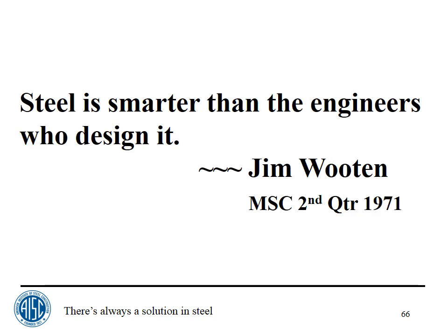Jim Wooten, an engineer who worked for a large fabricator in Little Rock, Arkansas, and passed away a few years ago, wrote an article called Wooten's Third Law that was kind of railing against some of the things that he was seeing engineers requiring, hotspot stresses and things of that sort. And he said that steel was smarter than the engineers who designed it. Again, this is a little bit of hyperbole, but the point was that if a material is ductile, then if you have hotspot stresses in various places, they can redistribute, and the structure will be satisfactory.